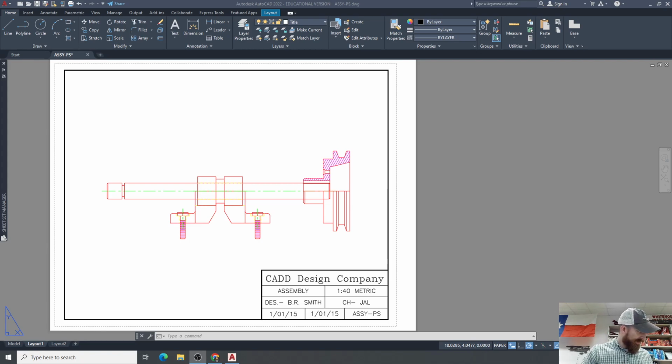Got some notes here. So in AutoCAD, the term plotting can refer to plotting on a plot device, like we just talked about, or printing with a printer, like a LaserJet printer. There's two methods to create and save plot specifications for a layout. So you can see I've got a sample layout here. This is like an axle assembly, and what I'm going to do is print it or plot it. And there's a lot of different ways to do this, right? So let's just start with this.